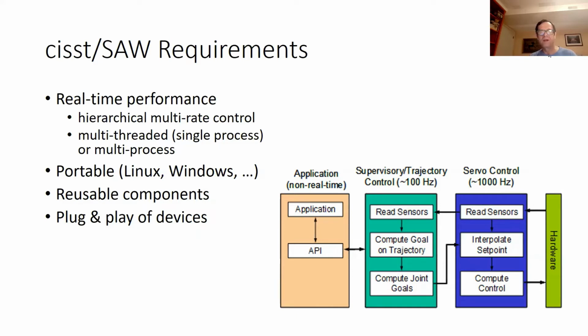And we were at that time really focused, especially with computing hardware of those days, on being able to get real-time performance, especially to do the typical kind of hierarchical multi-rate control you'd find in robot systems, where you're say servo control at kilohertz or more, a mid-level control at really more like a few hundred hertz, and then you have your application, which generally is non-real time.